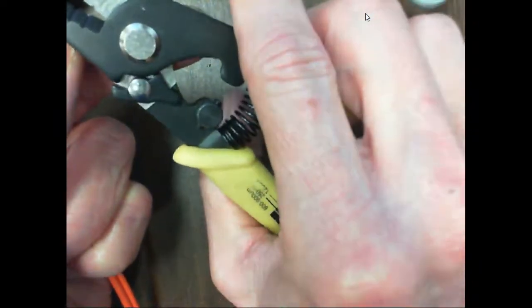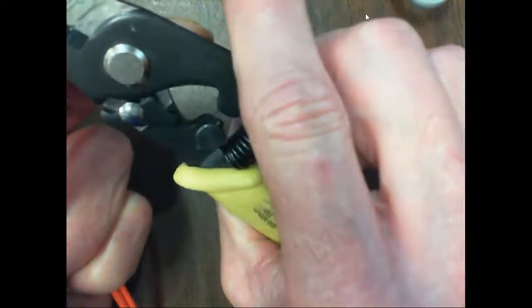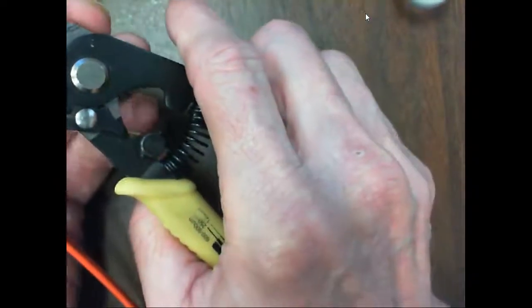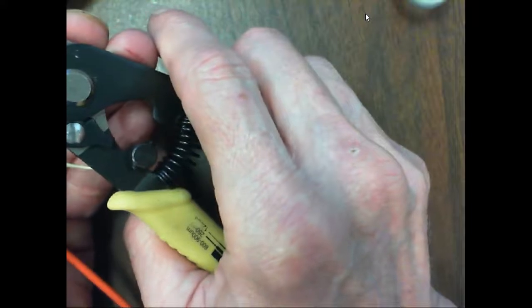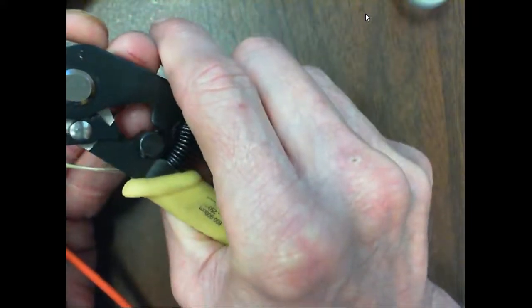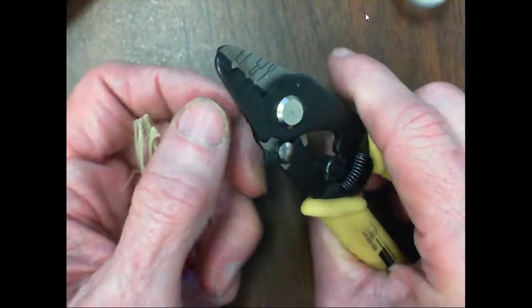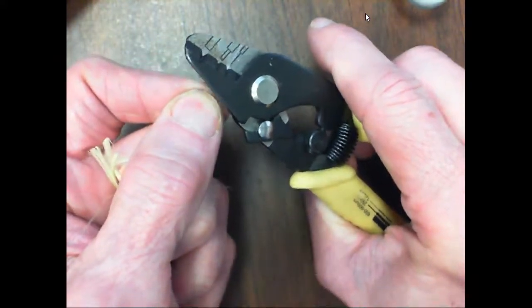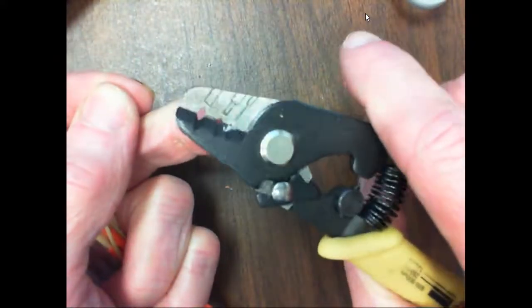So what I'm going to do is go down to the next one. Got to be real careful because you can cut it in a heartbeat. What I'm going to do is deliberately, we would do this about a 1/4 inch at a time. We do it at an angle. Can y'all see them at an angle? And then we pull it out. And that's the buffer coating right there.